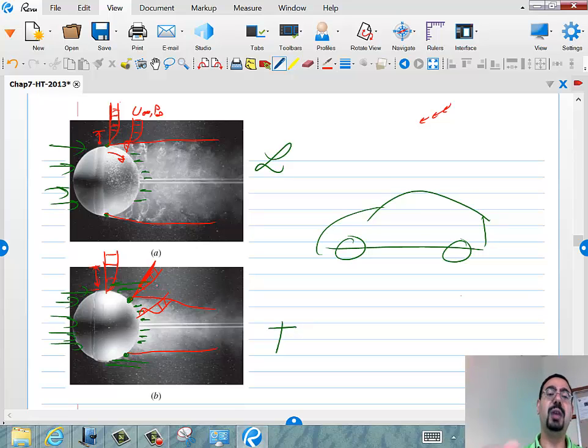Here he's basically showing us by experiments the difference between laminar and turbulent boundary layer. So with the laminar boundary layer, the flow separates here. With the turbulent boundary layer, I don't know whether you can see, the flow separates further down. So you see how the wake is actually smaller than this one? Right? So the same idea is behind those cars, you know, they try to make the flow separate much later or much farther.